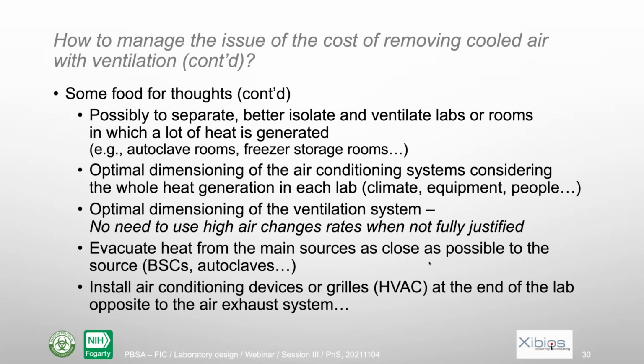Another trick is that you should evacuate heat from the main sources as close as possible to the source. And I gave the example of the biosafety cabinet and the autoclave. And also you should install the air conditioning device, so the system that is cooling the air, at the opposite end versus the ventilation system. So you should extract the air as far as possible from the place where the cool air is generated.